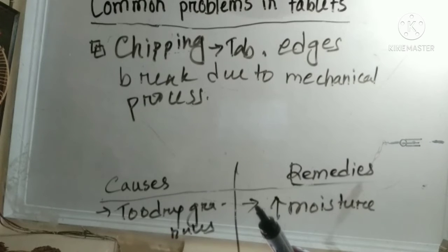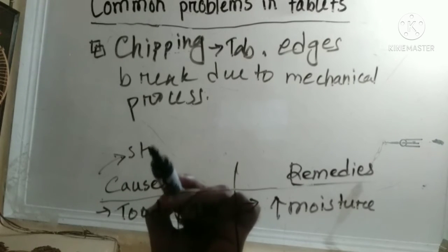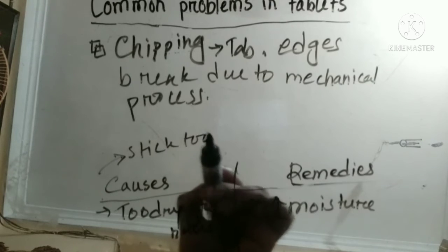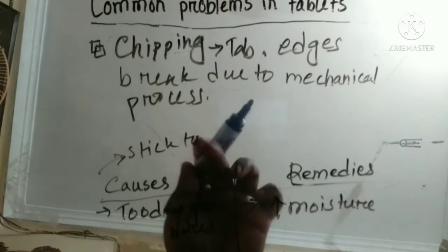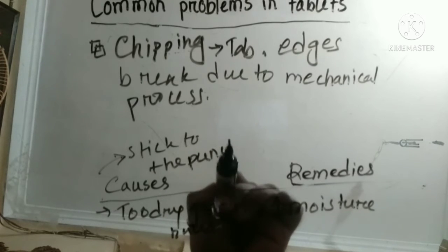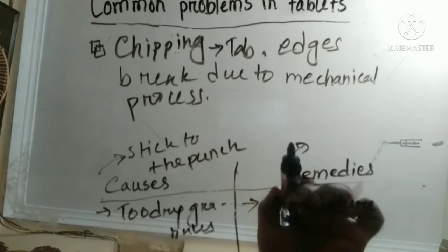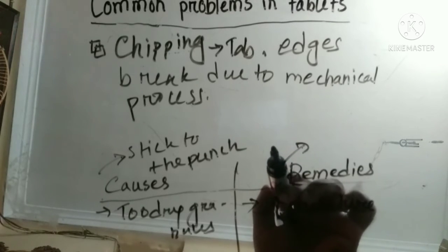Then another cause is some granules stick to the punch. Okay, some granules actually stick to the punch. So what will be our remedy? So we have to dry.